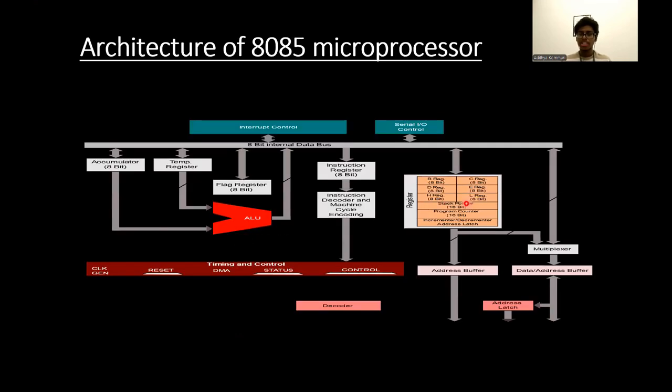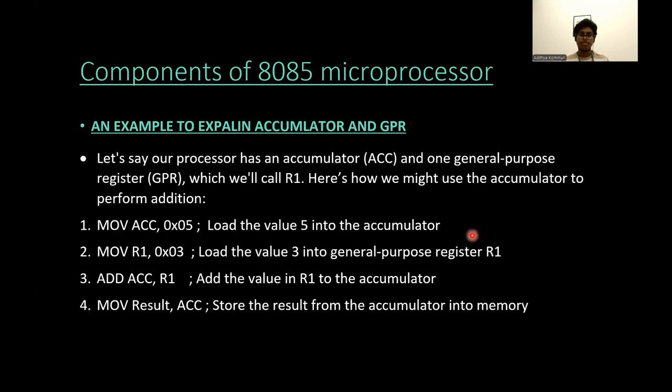Below the program counter register, we have another 16-bit register called the increment and decrement address latch or register. We have seen in the address, stack pointer and program counter that we have several cases where we need to increment or decrement the address of the instructions which are stored in it. These are performed with the help of the increment and decrement address latch.